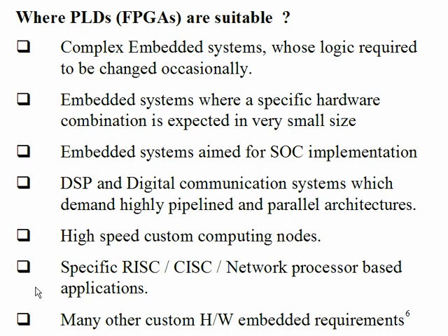Of course, that is true in the case of a RISC processor also, but what I am trying to say is, when you are using a RISC processor, more effort will be required by the person who is developing the application, and there is a possibility that he can fine tune the application to achieve the peak possible speeds. But when you talk about CISC, the programmer generally takes a lesser burden, but you don't get that much fine tuning. After some level, you can't improve the performance on a CISC. That is the one thing.